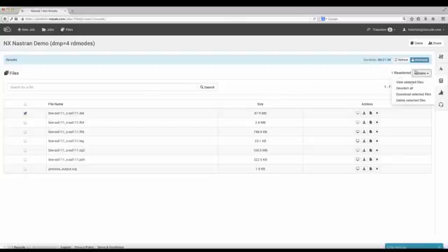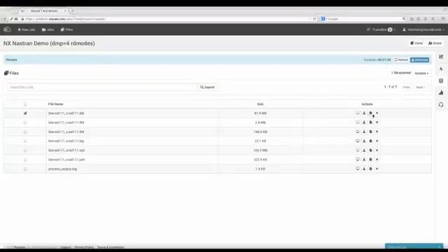You can select an individual results file to download, view the file directly in the browser, use it as an input file for a new simulation, or delete it from your account. You can also download the full set of results in the top blue bar. The final two components are the share and clone buttons. The clone button makes an exact copy of everything in your job, input decks, software, hardware, etc., and puts the duplicate in your own Rescale account.